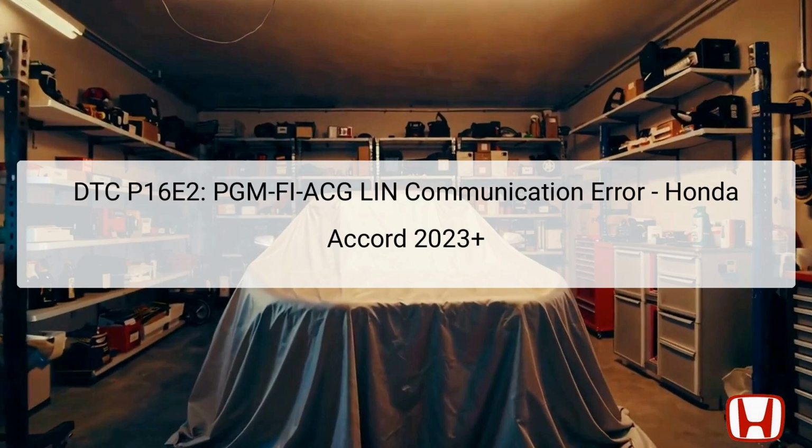The Diagnostic Trouble Code, DTC P16E2, refers to a PGM-FI-ACG LIN communication error specifically related to the Honda Accord models from 2023 and beyond. This code arises when the Powertrain Control Module, PCM, fails to properly receive signals from the alternator through the Local Interconnect Network, LIN. The LIN is a low-speed communication network used in vehicles to connect various electronic components.